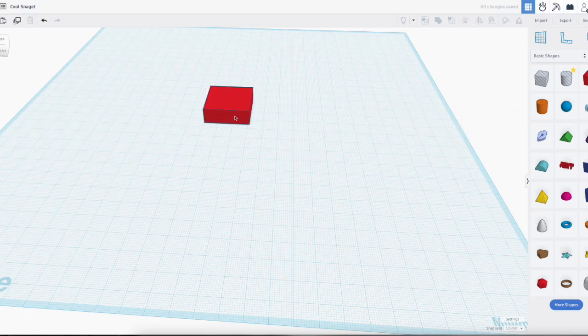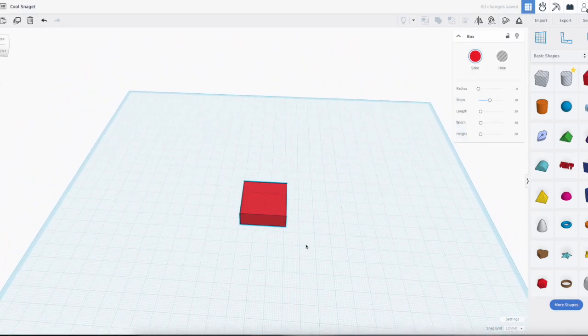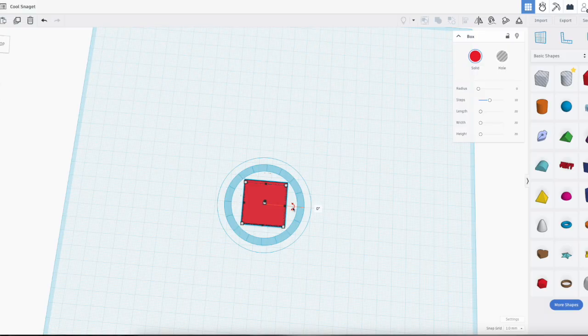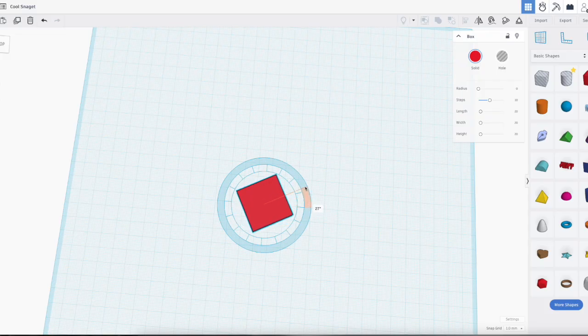Okay. If I click on this, I'm going to use Shift and drag, and I'm going to go above it by right-clicking and pulling down. Notice this side-to-side arrow or up and down arrow here. If I hover over that and click on it, I can now rotate this box. If my mouse is inside of this inner ring, it's going to go by those larger tick marks, which are 22.5 degrees. If I bring my mouse to the outside here, I can go by individual degrees now. And if I hold down Shift, I can go by even larger chunks. Okay, so that is rotating.